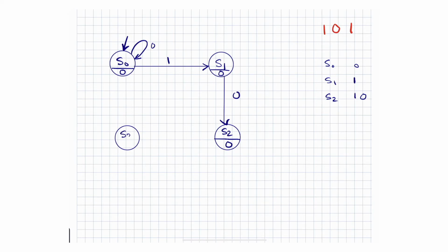S3 in here will tell me, okay, if you have this input as a 1, S3 is actually remembering 1 followed by 0 followed by 1. All right, so now all I have to do is say that the output should be 1 in here, and I believe I'm sort of done. All I have to do is fill out the rest of the arrows or the transitions. So let's stop. I think S0 is done. I have the 0, I have the 1.